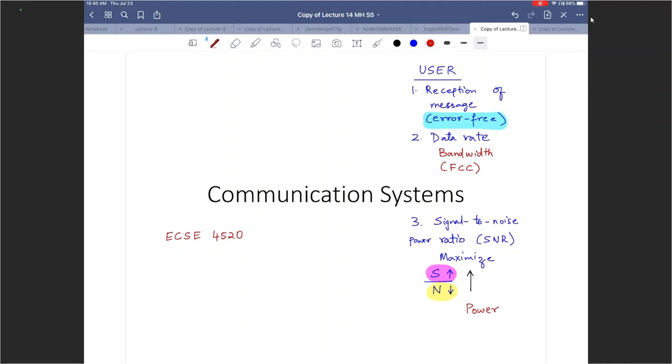Max says you can balance the transmission medium to eliminate noise is a theoretical concept. Minimizing noise is a practical concept. Yes, mitigation is fine. Minimizing is fine, but eliminating noise can only happen ideally, not in practice. Just imagine, if you want to make thermal noise zero, and thermal noise is present everywhere, then you have to reduce the temperature of operation by a lot, and that might not be practical. If I say that you can use your cell phone, but you have to use it from a freezer, you will probably not appreciate that, right? So there are limitations on how much you can reduce noise. Completely eliminating it is just a theoretical concept.